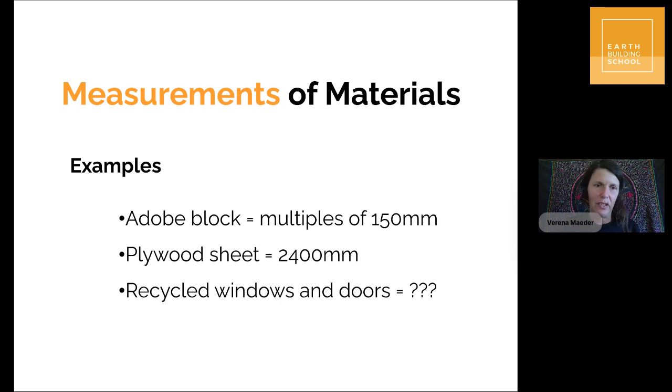And I mentioned recycled doors and windows. If you're going to use this for the sake of the design, you might not know the sizes, so just assume, or use something out of your app, or look up standard window and door sizes. When you're then going to build and you're using recycled windows and doors, it is very useful to have the exact measurement and then design to that.